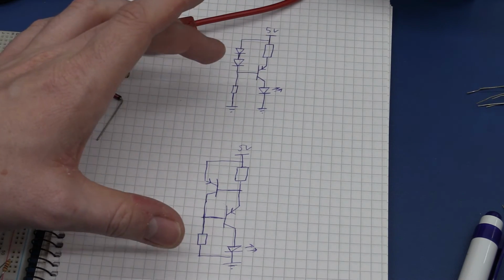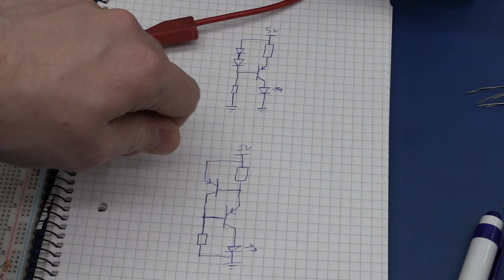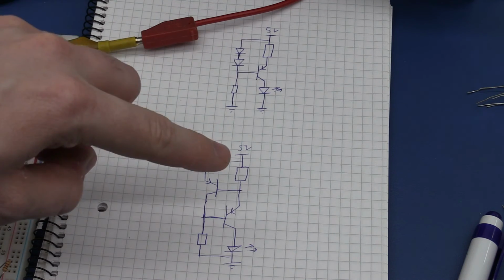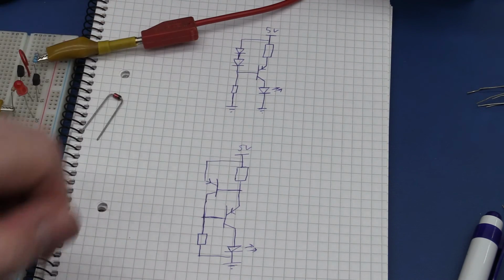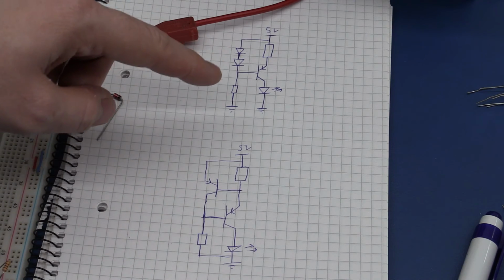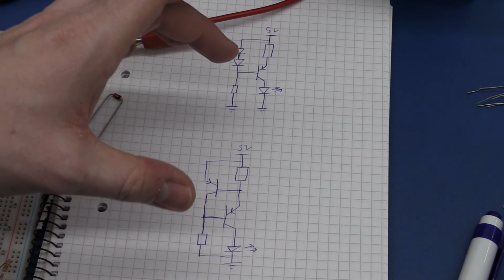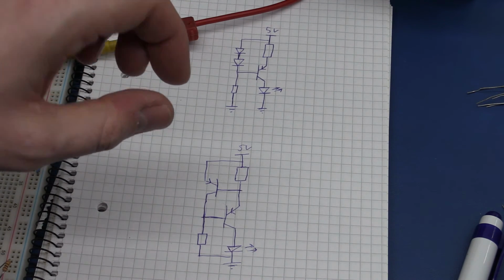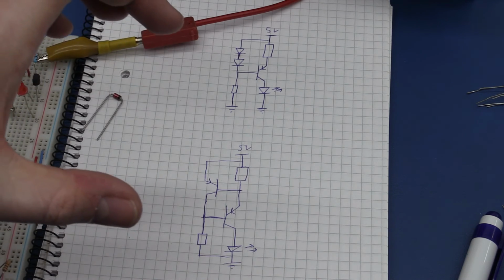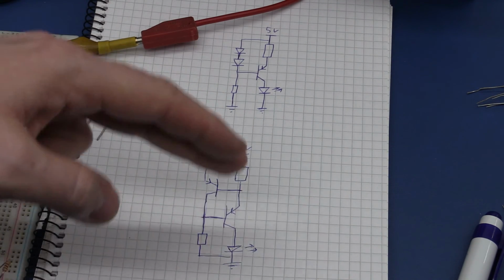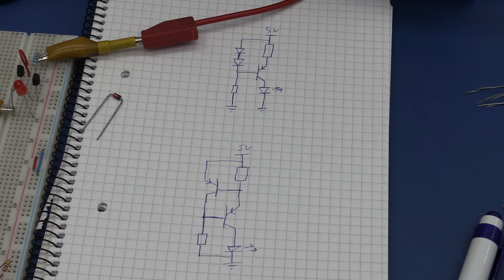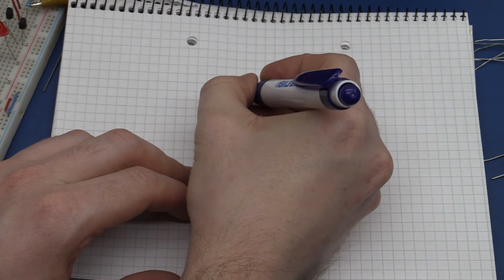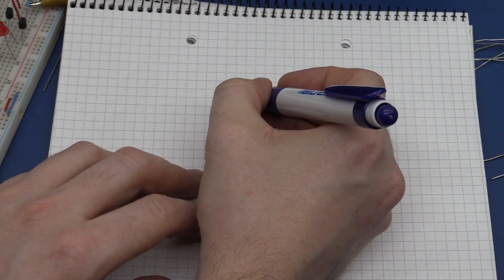For low power, low current, you can use a potentiometer, that would be fine. But for higher current, that requires a potentiometer that can handle that current, and that can be quite expensive and hard to get. So could we make a circuit in a way that allows us to adjust the current by a low power potentiometer, and then the regulator would rely on fixed components? So if we allow ourselves to use an op-amp, then it's pretty easy.